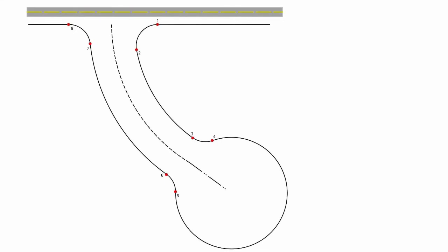After locating these points, along the curve, centers should be located. The center of the cul-de-sac is the easiest to locate. It is at the end of the forward tangent. Since the large curve starts at the edge of the road right-of-way that has an intersection of 90 degrees, the center of the large curve must be located along the edge of the road right-of-way,